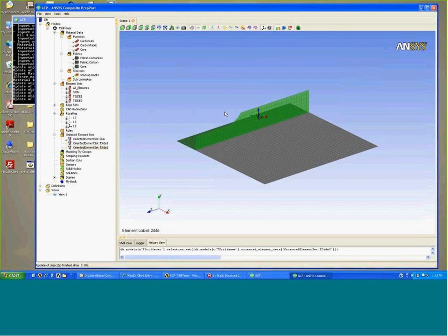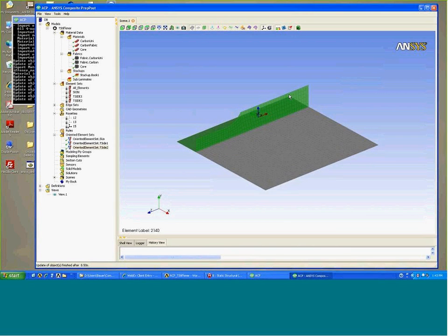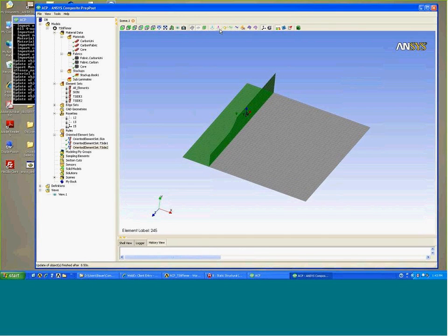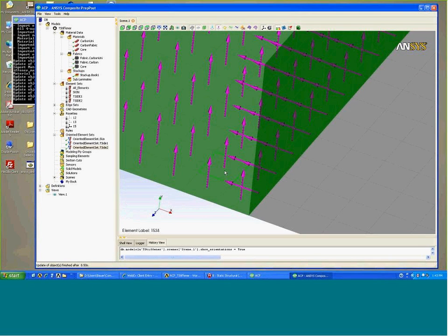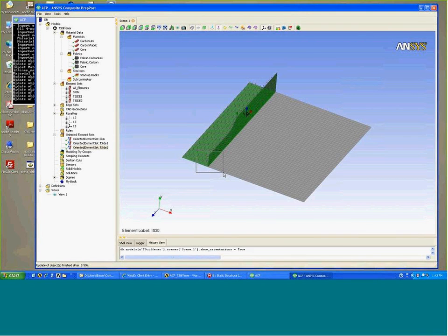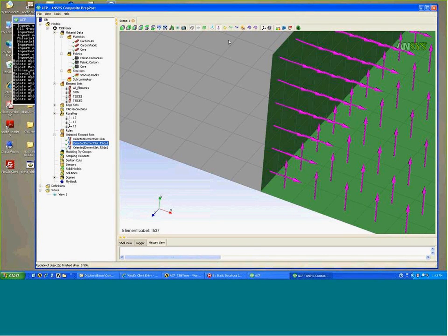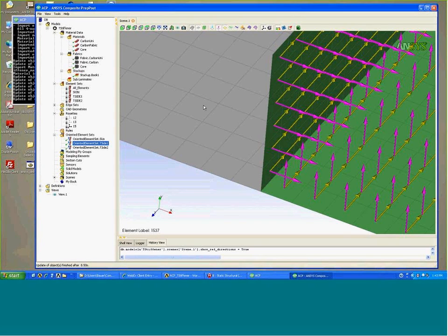Let's bring this into view, and before we view further, let's update our model as well as review our reference directions. Here we could see the four oriented element set T side 2. Here's our direction normal. On the upright face, it's upwards. On the skin side, it's upwards, and the upright, it's oriented to the left. And likewise, if we highlight the other, we have the proper normal direction. And with both, we also have the X direction in the proper direction as well.